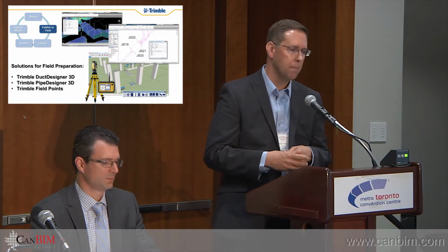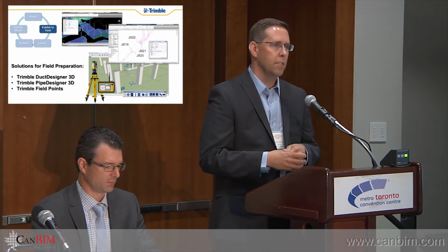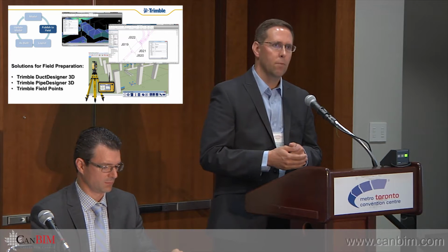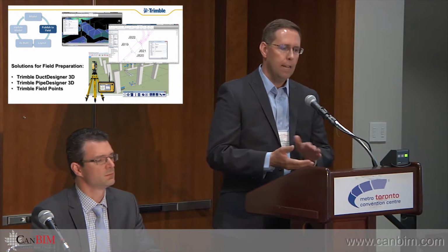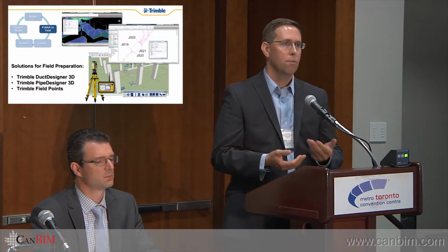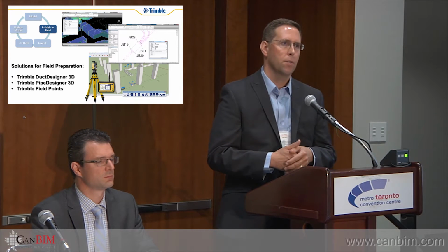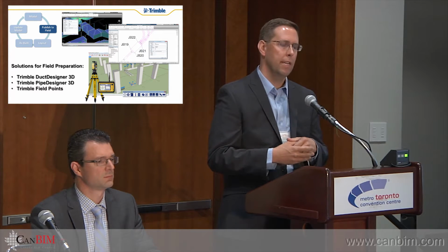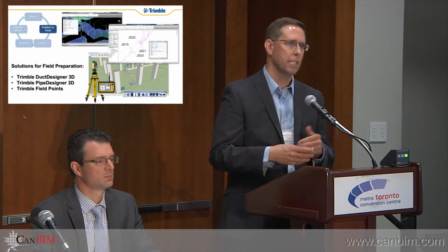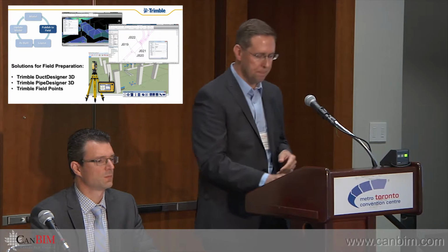And these are all the items that you want to have actually staked out in the field accurately using a robotic total station. For folks that are not using either DuctDesigner or PipeDesigner, we also have a program called Trimble Field Points, which allows you to have that as a plugin within either AutoCAD, Revit, or SketchUp. And then you can also create those same type of field points and have a direct integration of pushing that information out to the robotic total stations that are being used out in the construction site.